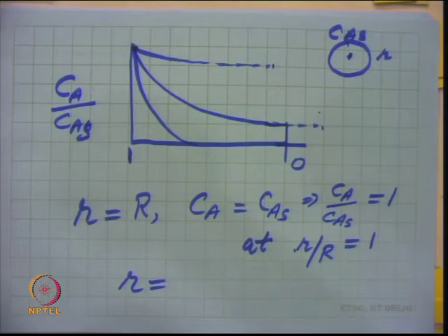Whether you look at the mass transfer resistance, you need to look at a definite size and shape of the catalyst, because you would like to have a large interfacial area and a large external surface area of the catalyst per unit volume, and that will depend on the shape and size of the particle. That is again important for the design of a catalyst particle.